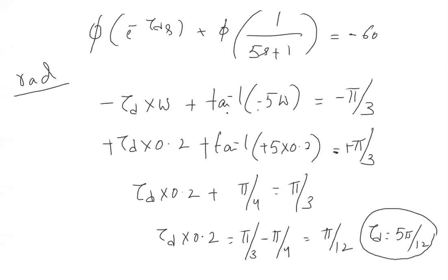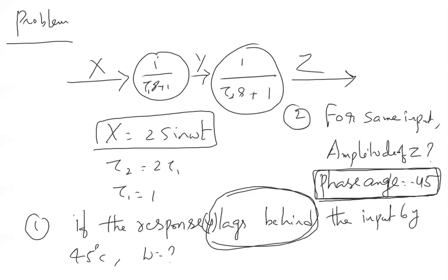No, we can't say yes. In the previous table, we can say that it is stable. Moreover, you don't need the frequency response to say whether it's stable or not. Look at the transfer function, 1 by s plus 1, 1 by 2s plus 1. What are the roots? One root will be minus 1, another root will be minus 1 by 2. Both are sitting on the left side of the imaginary axis. So that means this system is stable.